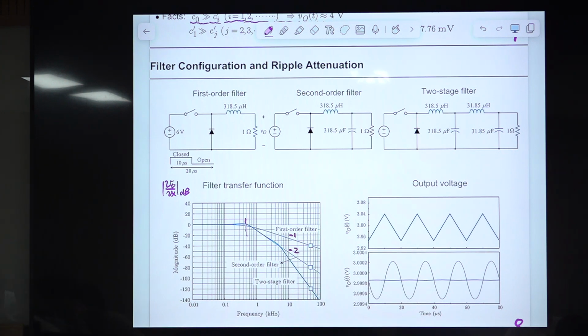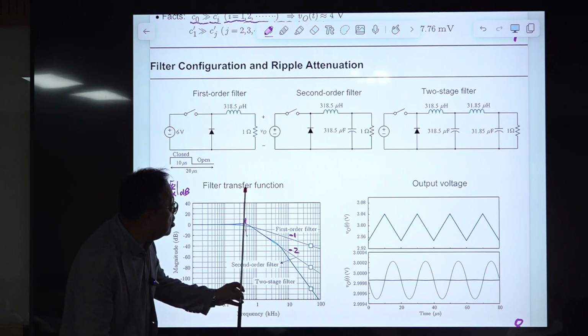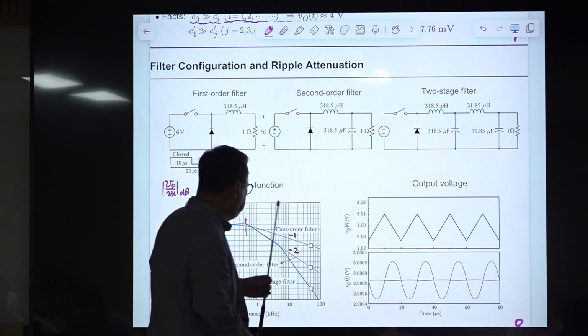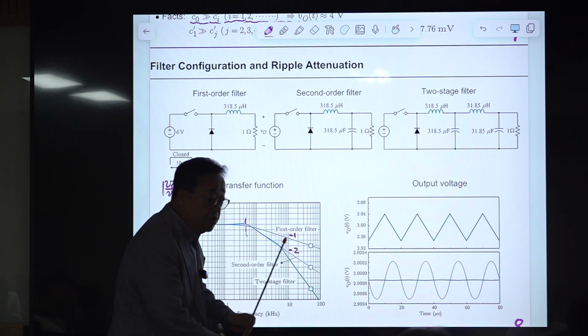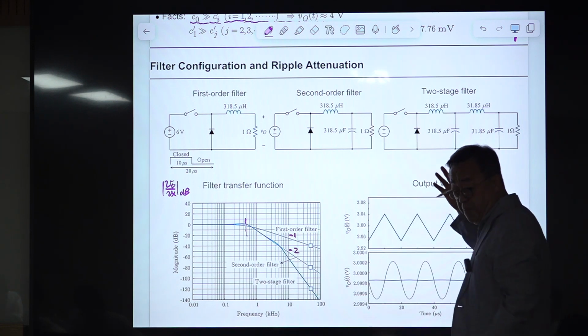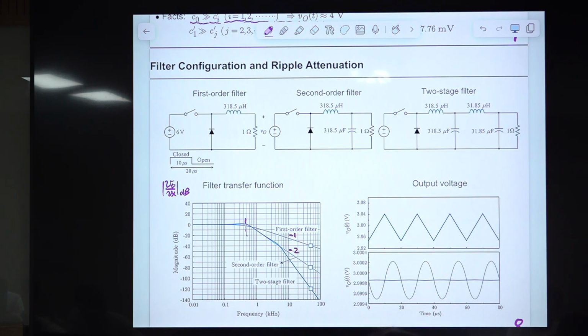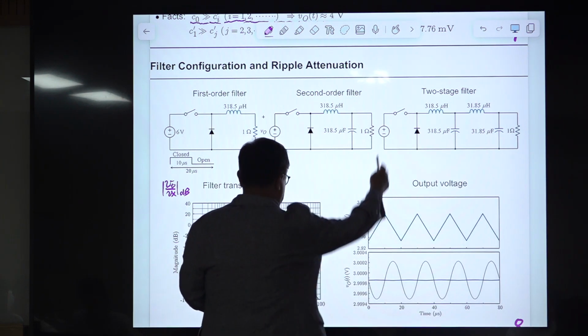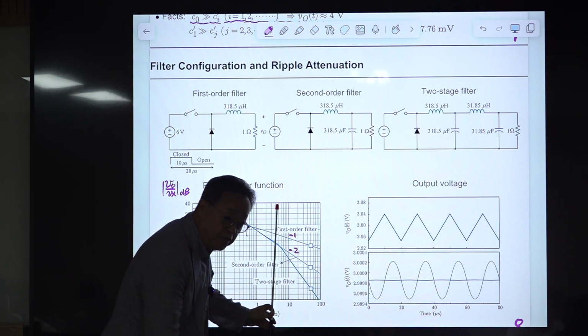With this two-stage second-order filter, you have the first double pole here, but because of this stage, you have another double pole here. We separate this part and this part, so this is possible. This is a very good approximation because the resonance frequencies, the pole frequencies of these two parts, are far apart. So we can recognize this transfer function has another double pole here.